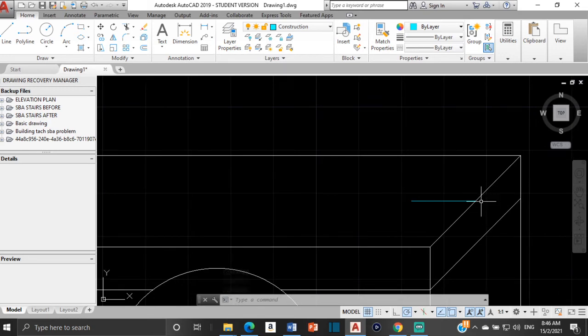So now this is 15, and it says that the diameter for the circle, which makes the button, is 20. So we're going to need to create a square to draw the circle. Let's create that square, and that square is going to be 20 by 20, since the circle has a diameter of 20. This is 15 here. This would be the center of our circle.